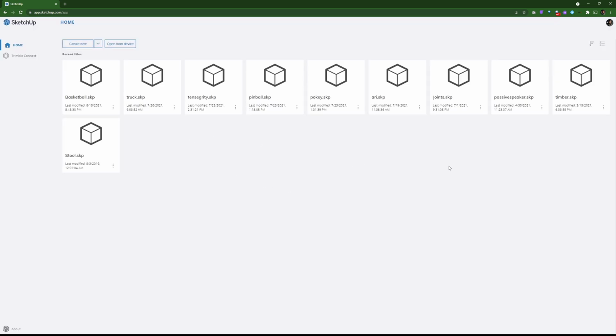You'll come to a screen like this. There's all the drawings we've done. You're going to click on the little arrow, the down arrow here. Make sure you're on millimeters. I know that you'll be tempted to pick centimeters, but do not. We don't want to work in centimeters. We want to work in millimeters for this drawing.